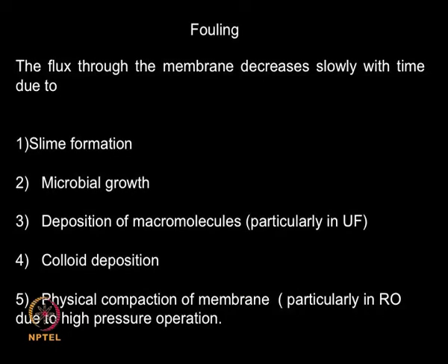Fouling happens because of so many factors. Fouling happens because of bacterial material present, because of the dissolved salts that are present, because of changes in pH which will allow your salt to precipitate out, because of colloidal suspension which gets agglomerated, and so on. So all these factors lead to fouling, and there is going to be a deposit of material on the upstream surface of your membrane. So the entire membrane filtration gets slowed down as time goes on.